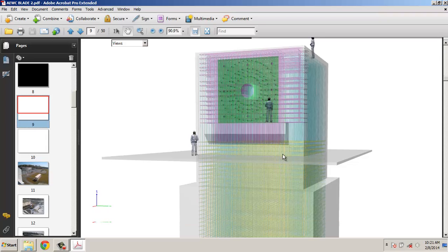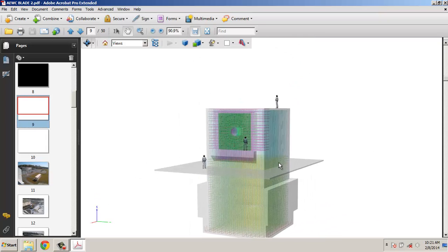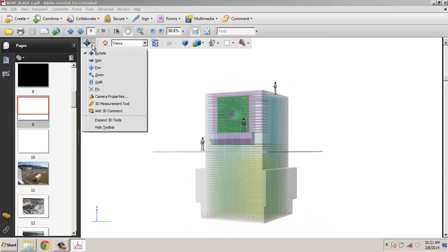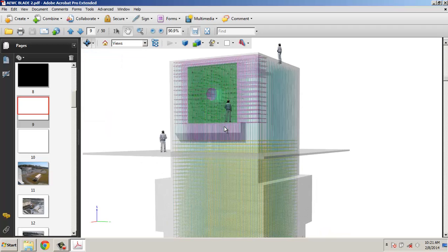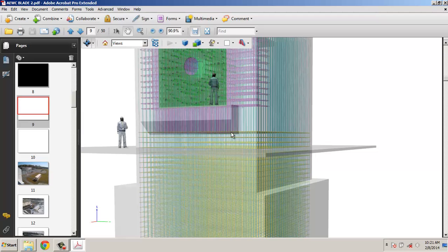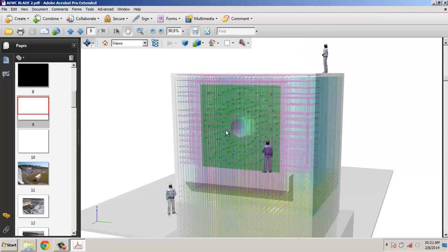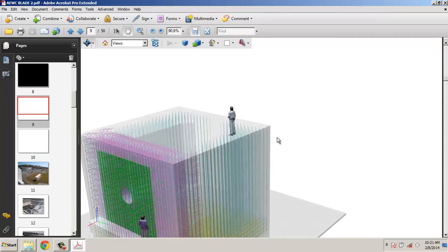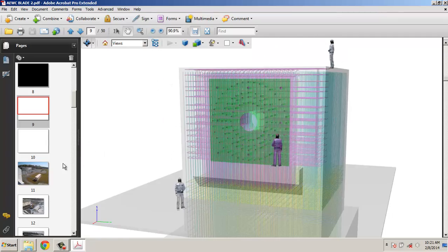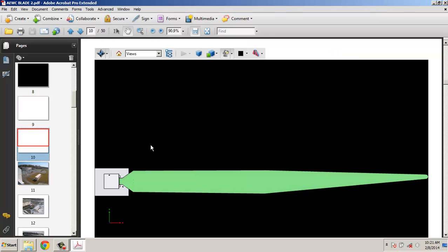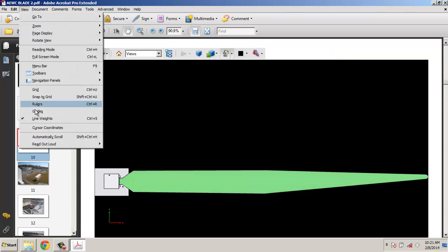So this is, if we look at this, I pulled this off the drawing, but this is the reinforcing that is in this piece. So you can see how much reinforcing steel is in this concrete, to the point where the aggregate needed to be so small to make sure that it could fit down in between the reinforcing steel. So you can see there's just a lot of steel in here holding this plate in place. And why is that? Because this is, and I'll bring this view up to full screen.